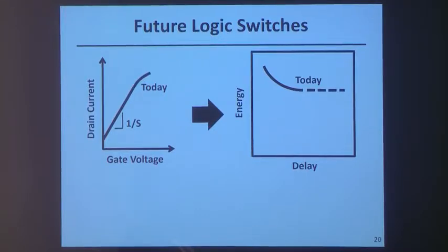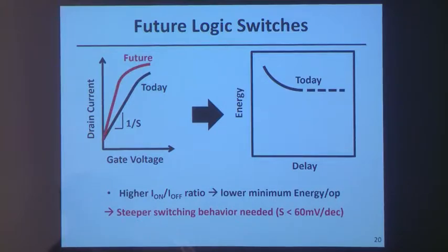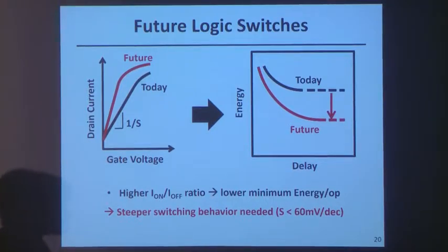And another issue is that if the operating voltage cannot be aggressively reduced, then the power density is going to go up as you pack more transistors together. And there's, of course, good work being done on tunneling transistors, negative capacitance transistors, to really steepen further the subthreshold swing so we can further lower the operating voltage. And once you lower the operating voltage below the threshold voltage, you don't get any benefits. So if we can, with steeper switching devices, lower the operating voltage further, we can reduce the energy per operation for a given level of performance to overcome the power density challenge for CMOS.